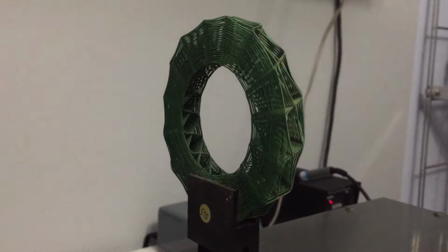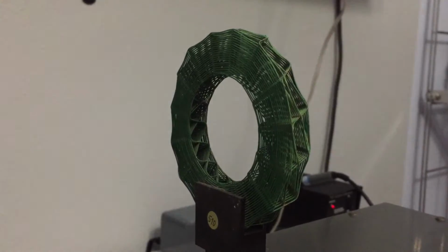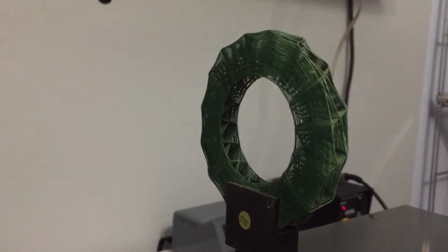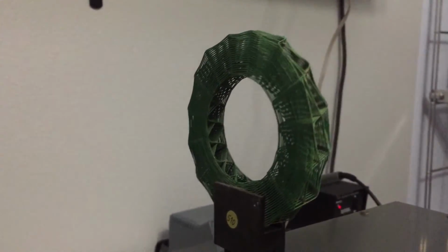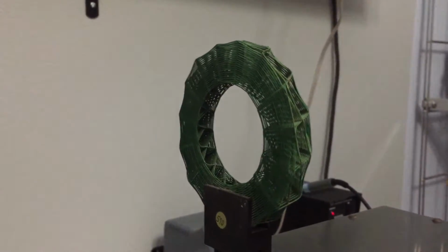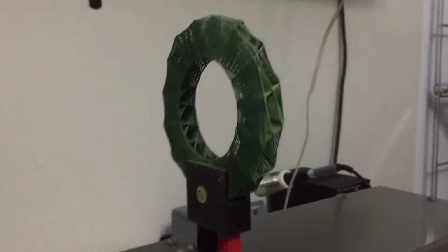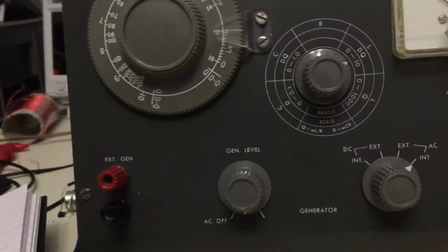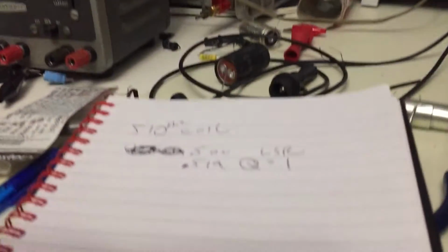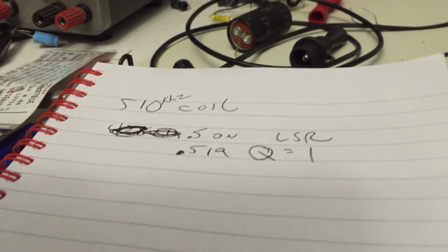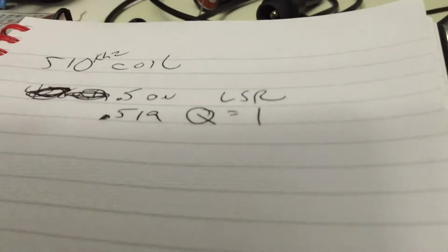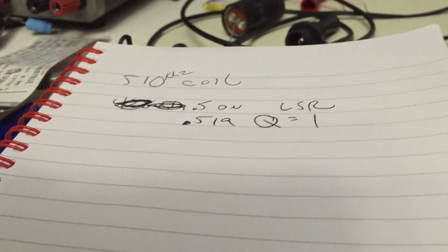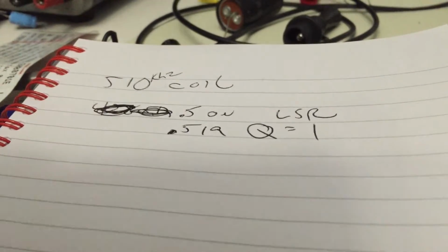It came with a couple of coils for this set, and this is the resonance of a tank circuit along with the variable capacitor supplied with this coil or the radio. So I know in and around where the resonance is. What I'm using is the 1000 hertz, or the kilohertz, that comes with this unit to tune it in like I always do. And it happens to be that on my LCR, it reads 0.5 millihenries, or 500 microhenries, right?